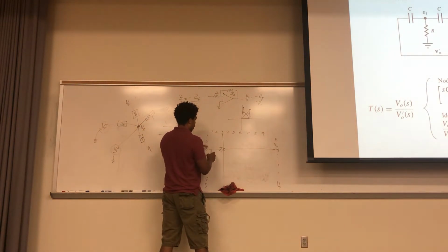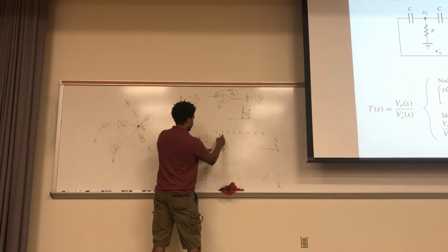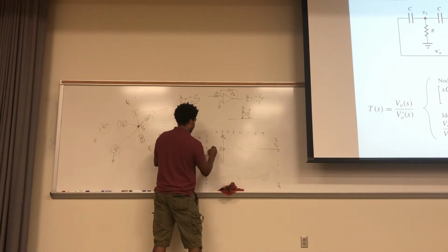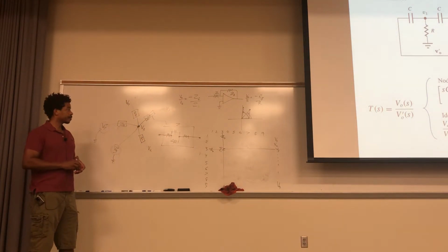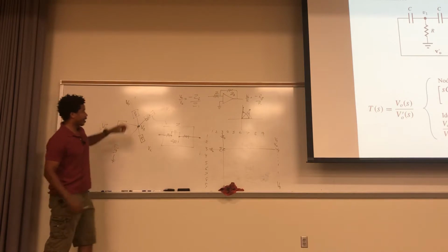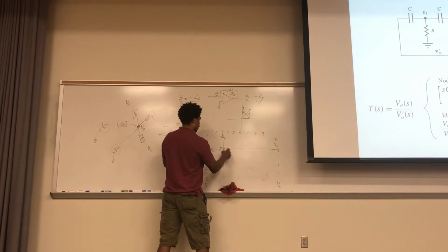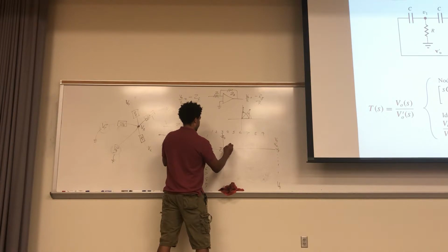So at 3 and 1, that corresponds to this place and this place. So right here and here, I'm going to put a negative Z4 and a negative Z4. You have to do it twice, in both places. Okay? And then for the cross term between V3 and V4, you put a Z3, right? So for 4, I put a negative Z3, and then also I have to do the same thing here.